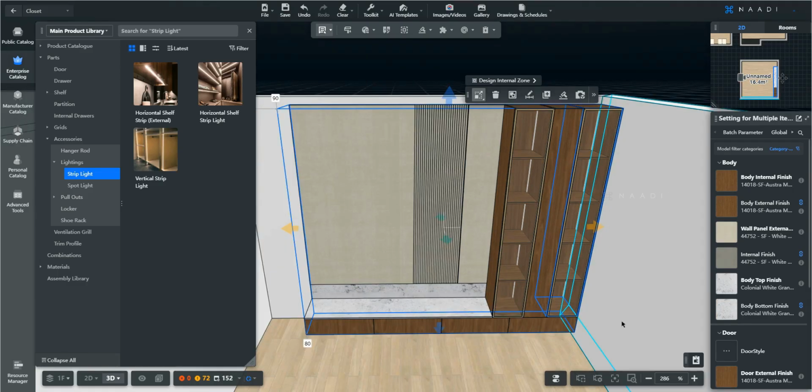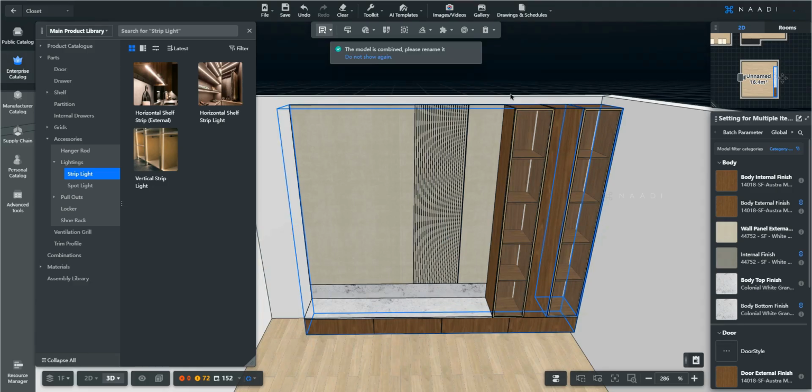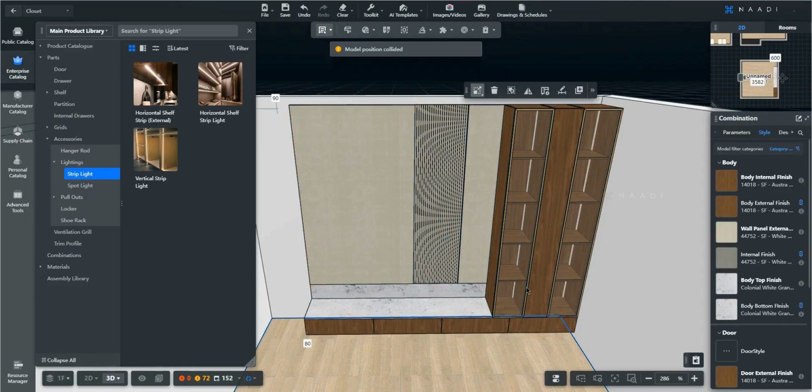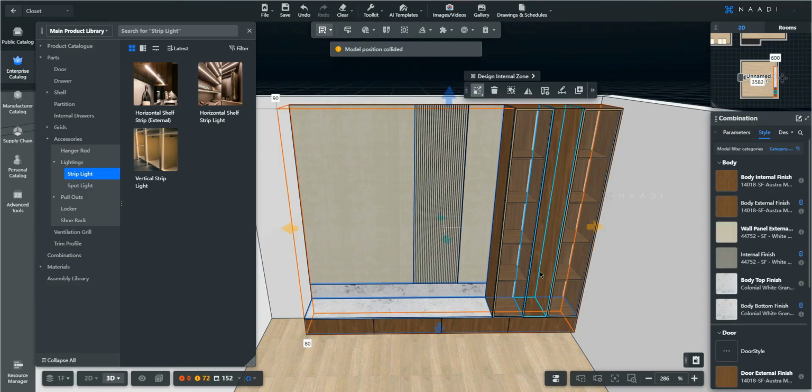Okay. But anyways, if you have multi-selected these cabinets, in the floating window, can you see there is this option named grouping? Shortcut is Ctrl G. Just click it. This will precisely group these cabinets. And once you group them, if you just select this cabinet, can you see that the entire group will be selected? Not the individual cabinet, but the entire TV unit group will be selected.